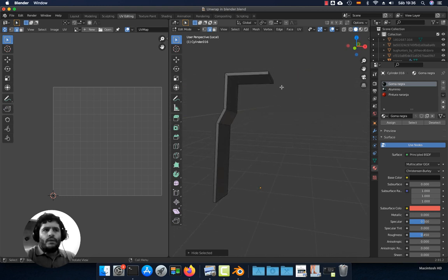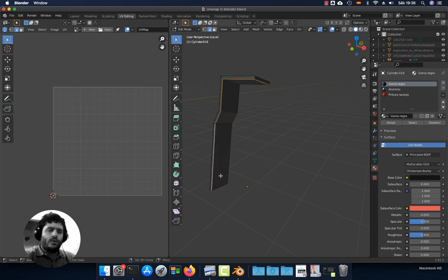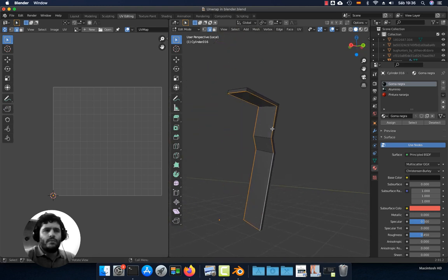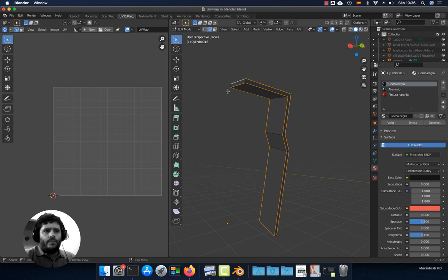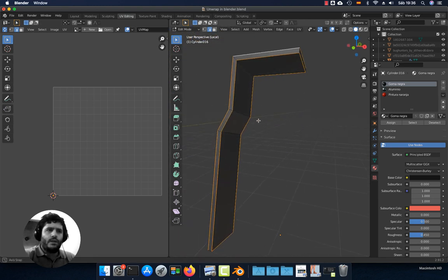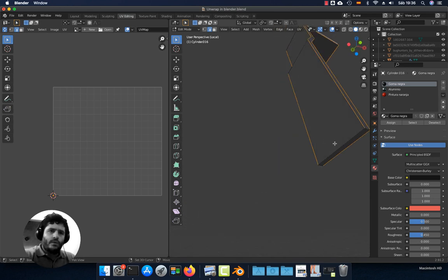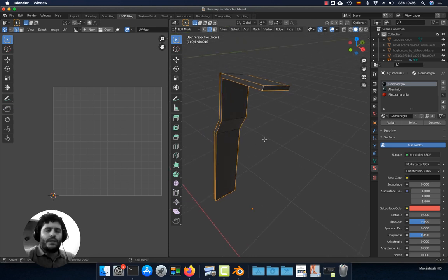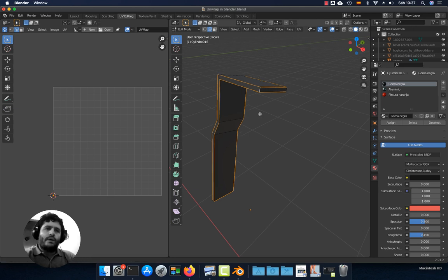Okay, this is like a box, so we can do the same. Select all the perimeter, Alt and click, Alt and click with Shift, like so. And now if we select one vertical edge, the width of this mesh will be able to unwrap also. So with all the edges selected, I'm going to press UV, mark seam, all the edges are red.